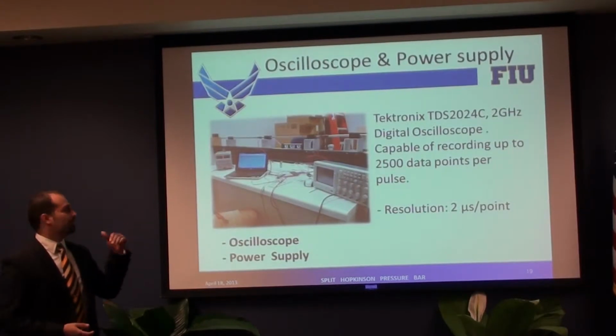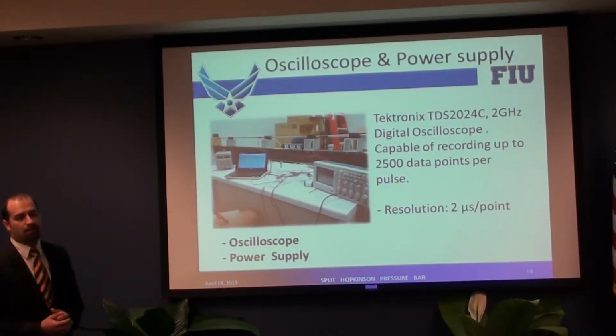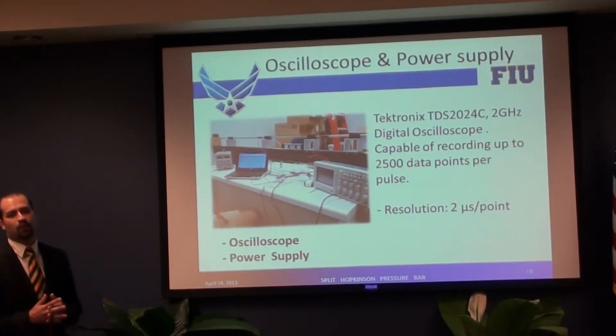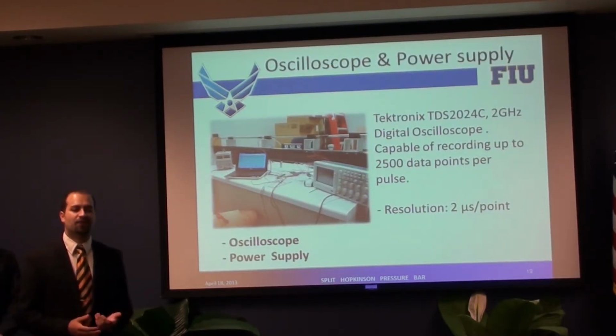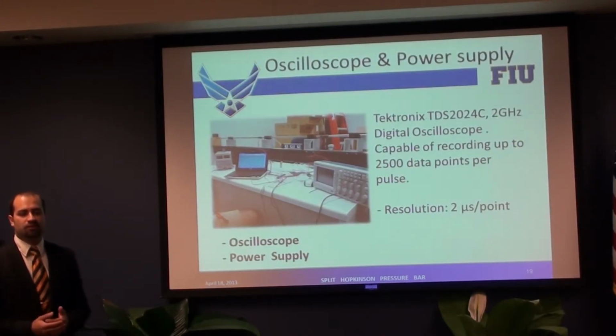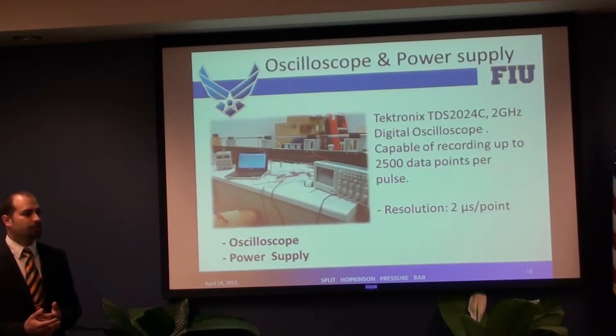For the data acquisition, we're using a 2 gigahertz digital oscilloscope that is capable of recording up to 2,500 points per pulse. The resolution that we're going to use is 2 microseconds per point.